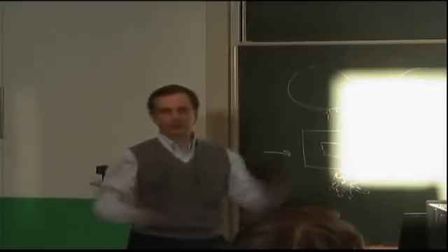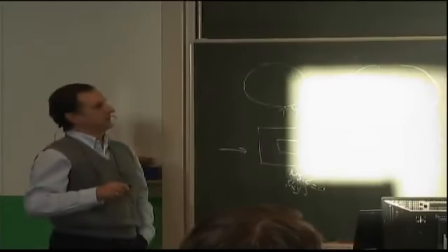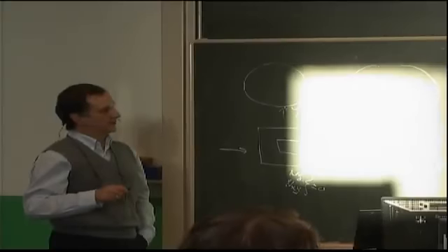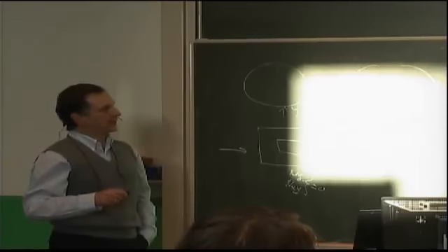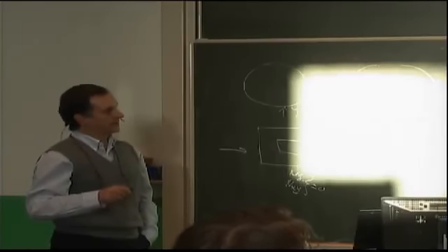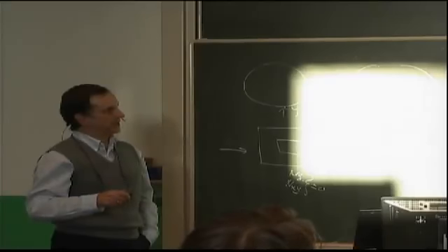And we solved it. We used some kind of matrix inversion or Gaussian elimination to solve the system of equations. How good is it? Again, we will compare with finite elements. The center layup, again, is all fabric plies, with 5 plies at 45 degrees, 2 at 90s, and then another 5. The perimeter is thinner. It's the same as the center, but instead of 5 plies on the outside, it has a single ply on the outside.